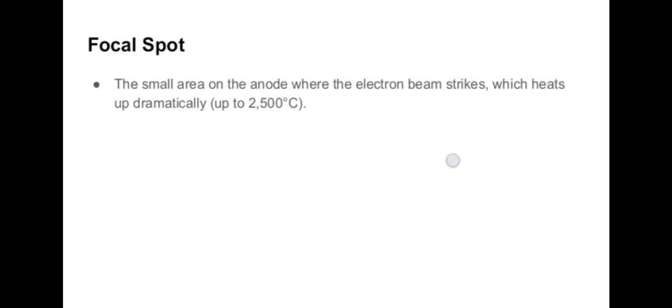When the X-ray unit is turned on, the motor alone is energized first for a few seconds until the rotor reaches its operating speed. Then a high voltage is applied to the tube for the required exposure. After the exposure, the rotor is slowed down quickly by dynamic braking to avoid wear in the bearings.